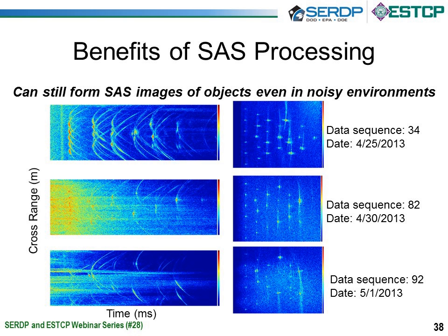Now on this slide, you can see some examples of raw data and the corresponding beamformed imagery. And the point is to show that because SAS is what I'll call an integrative technique, which means that we're going to be looking at the acoustic information from signals as we move along a trajectory, we can average those signals. This is essentially what the match filtering operation is doing.